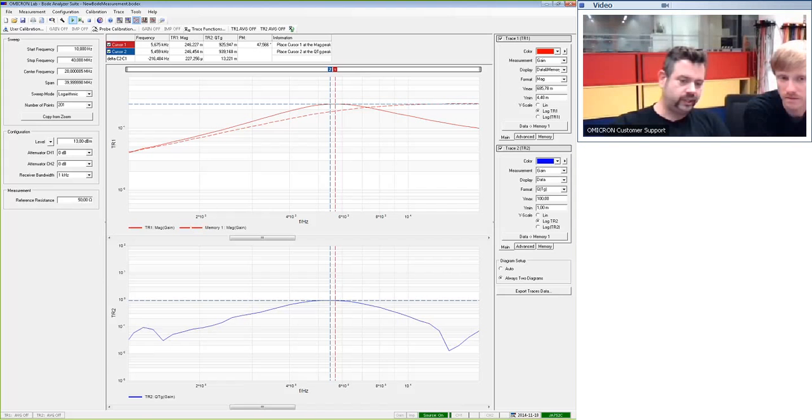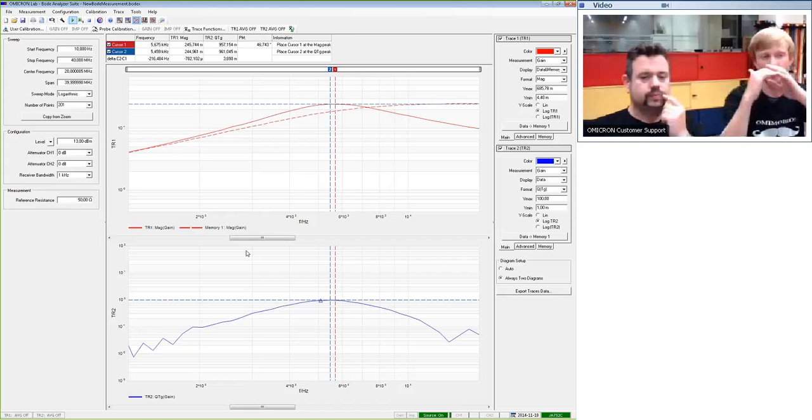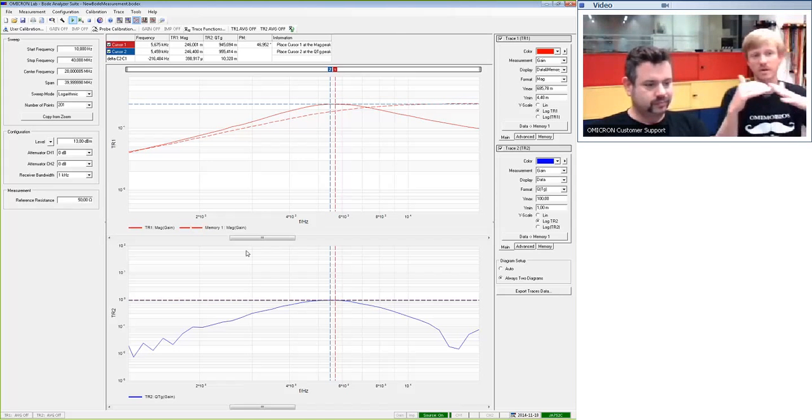And as you can see, here you already can see the single measurement points, and between the measurement points there is linear interpolation. So if I would use the jump to peak function, it would jump to one point, but not necessarily to the highest point, and also not to the center of our peaking. And we want to have the cursor at the center of our peaking, so that the shape of the curve is symmetric on both sides.